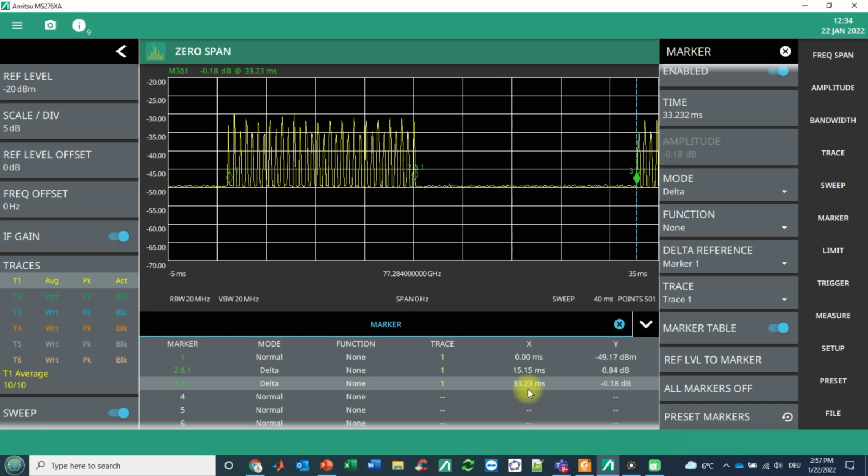So these are the essential parameters that we need to recap later on if we are going back into the frequency domain in order to measure the channel power of this device. So let's now continue, and in the next step we would like to get a feeling about the average power that we can detect here in the time domain. We are resetting therefore our markers.